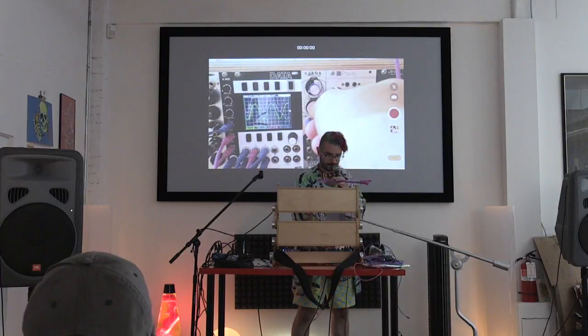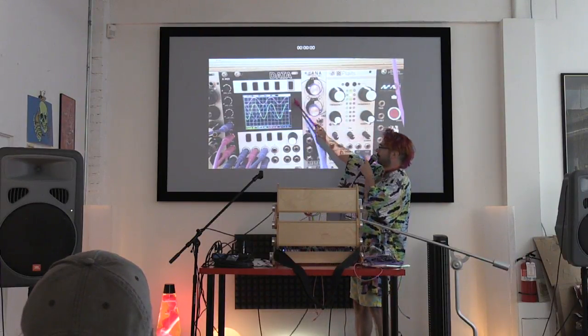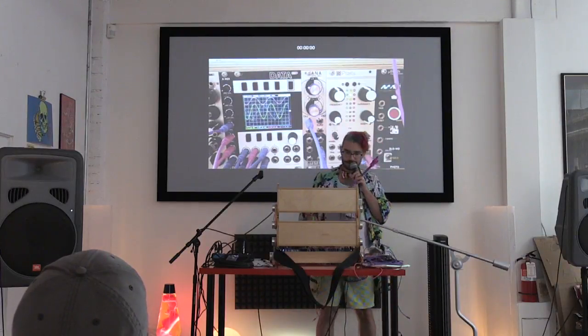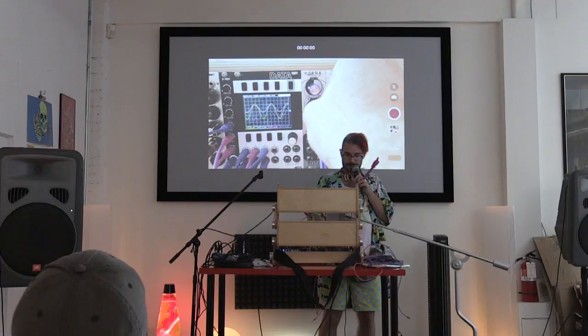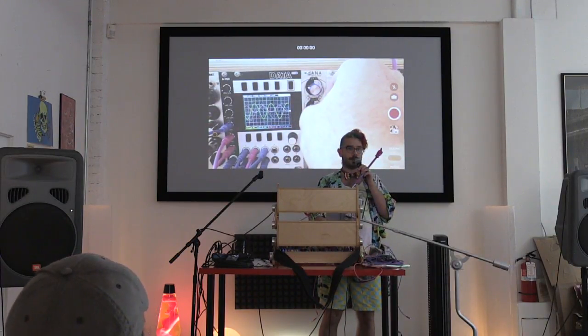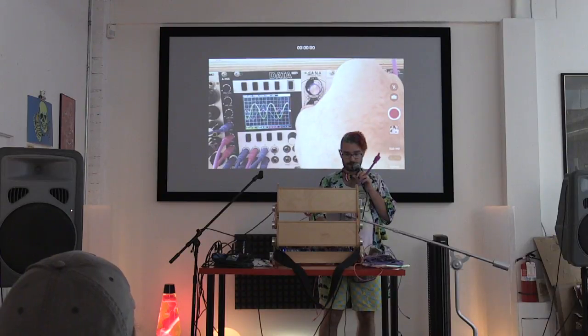Alright, so we've got a static voltage again, and the sine wave. So this triangle wave isn't doing anything. As the static voltage goes towards 0, it will kind of bounce off of 0 and head in the other direction. So it's basically what's known as a difference rectifier. And what that means is that you're subtracting the two inputs and then you're sending it through a rectifier.